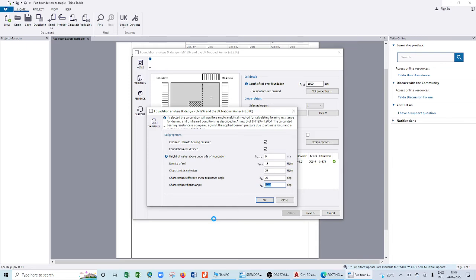Now, there are drawings that you always do where sometimes you find yourself doing your design based on assumption. You just assume the bearing capacity and you see. But you have to bear in mind that you have to visit the site and at least try to get the drawing and see what you find out there. If it's clay, you know when clay soaks water it becomes slippery. Meaning you need to know the relationship between the characteristic friction angle and the sliding effect of the foundation, how it increases or decreases for different types of soil. So now, you press OK.